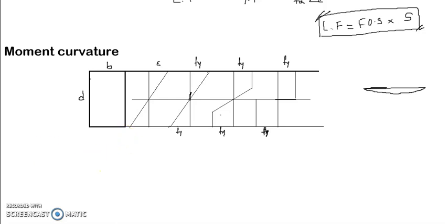So in the concepts of plastic analysis, we need to understand the moment curvature relationship in the plastic stage as well. Now, if you look at the strain profile here, this is the strain profile at the elastic state.